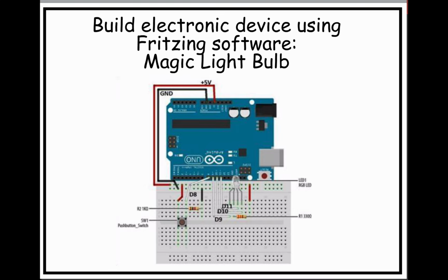So, again, going back to the block diagram philosophy, I have my switch on the left-hand side placed on the board, and then I have my RGB LED on the right side. And of course, in the middle, you can see here is the Arduino. So again, that's how I kind of lay out my board. Also, one thing I do is I try to keep everything kind of closely compact, meaning the wiring, all the components are pretty much in the same area, because if I wanted to add another part, then I have some more available space to do that, like on this side.